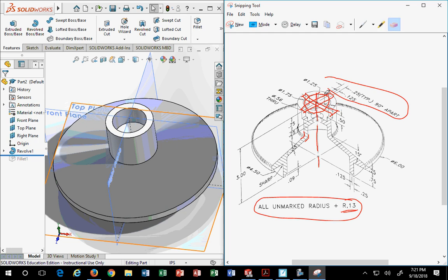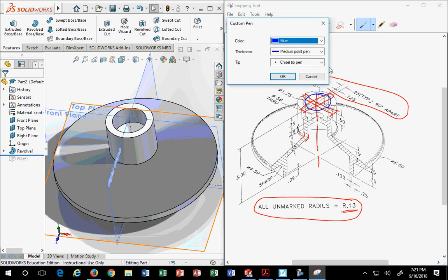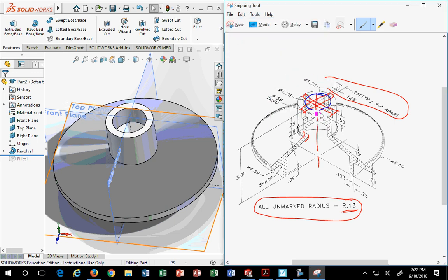So there's a lot of things when we think about how would we build this versus how would we draw this in CAD. To build this, I'd have this as a secondary operation. I'd be doing the red slots first, and then I'd be drilling that interior shape, and then of all things, let's find what colors we have. We're going to go with fuchsia. Then I would drill this as my last hole. See that? I'd make the slots first, the red slots.